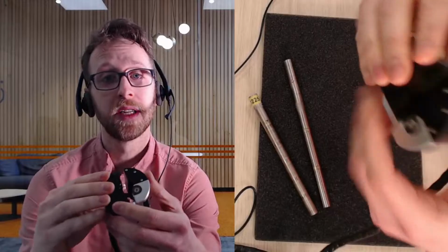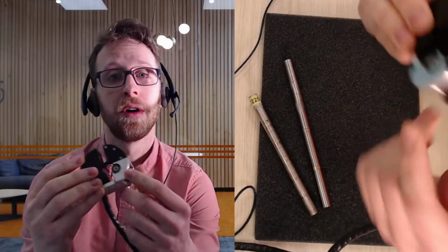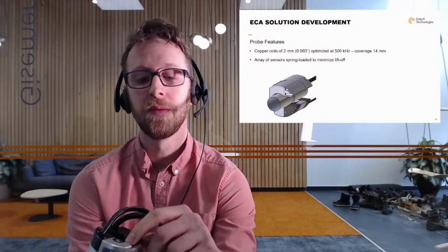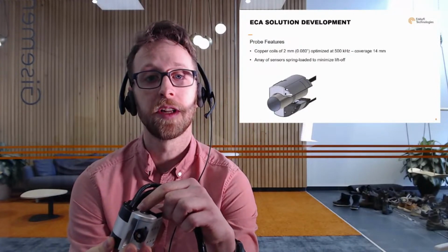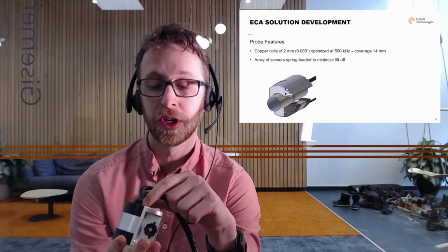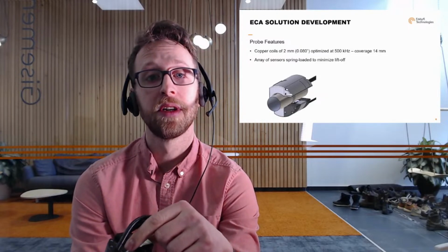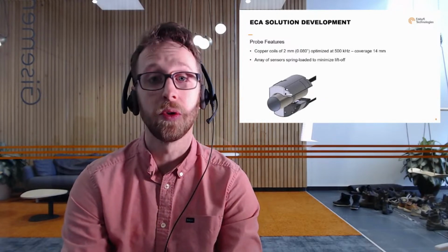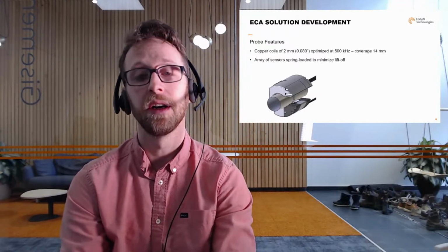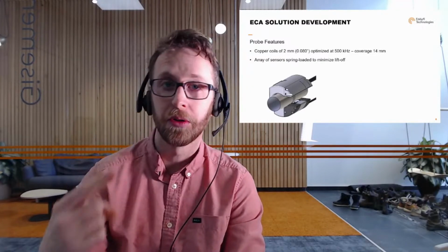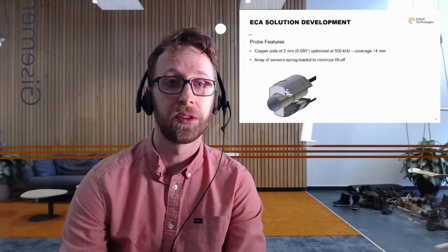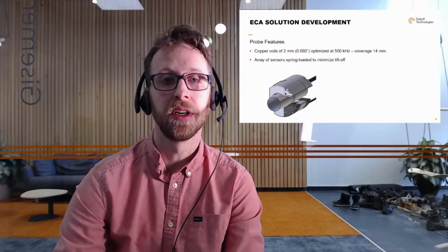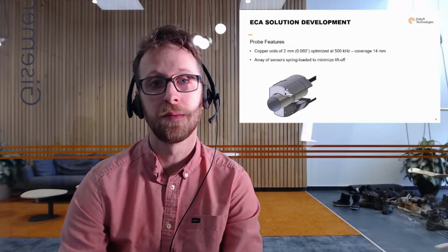To ensure stability during the scan, there are 4 wheels inside the probe. So there's 2 on each side, on the exterior of the probe here, and there's also 2 more on the top of the probe. And those are connected with a shaft that is connected to an encoder, which comes out here. So the encoder allows you to encode a scan and know the position of the crack. It allows you to use filters. So this is why we use an encoder that is inside this probe.